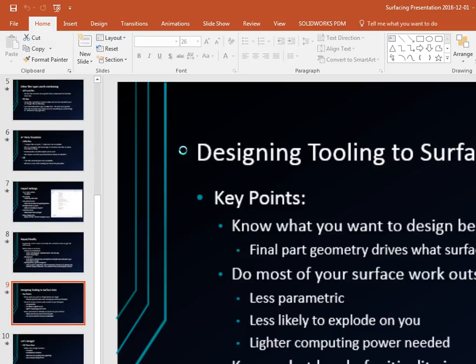That's an edge. So it's important when you're selecting stuff to have dynamic highlight on and also edges shown. Those are key things when you're working with surfaces. Helps you know what you're going to select. Do you guys know what that means, everybody? Okay, sweet. Yeah, so those faces, I've already got that saved off, so I'm just going to open it up. Top surfaces.IGES.